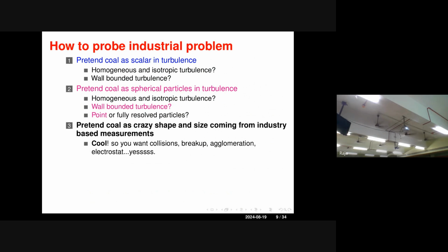But when you are using that, how are you going to really resolve it? You require billions of particles moving around. Right now, what we are talking about, whether particles come together, collide, what kind of lubrication, means already we are trivializing the problem to look at the local level. But the much bigger picture is that for any industrial problem, these particles have a variety of sizes. It's not one universal size. They will have distributions, from a few micrometers to a few millimeters to a few centimeters.